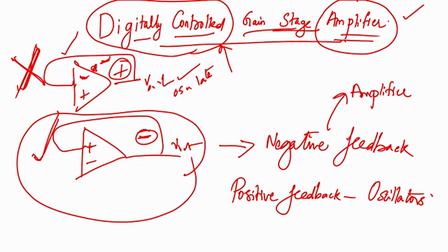So let us get our hands dirty and get into the circuit design. So now we know that our feedback should go to the positive terminal, because our output voltage itself is negative. So let us make the circuit. Our scheme will reverse, so this will be plus and this will be minus, and this will be our output voltage, V out.